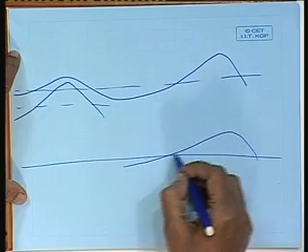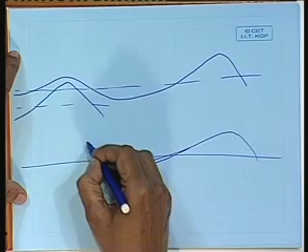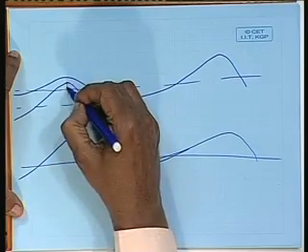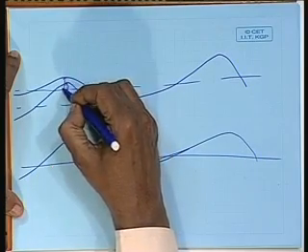This wave will come like this as it is coming, and here it will increase, this plus this, isn't it? And this is the aft of the ship. Therefore, it will push the ship forward. We have seen the pressure increase in the aft supports motion. Is that clear? That means the resistance will reduce.